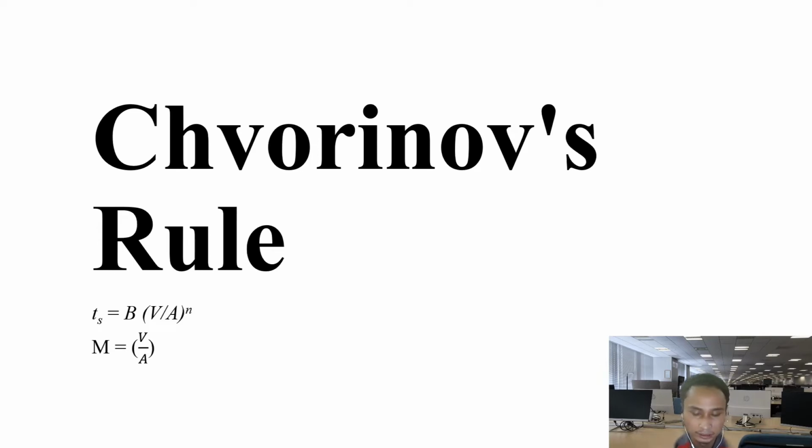The mold constant B depends on the initial temperature, density, thermal conductivity, heat capacity, and wall thickness of both the metal and mold. The unit of the mold constant B is seconds per meter squared. So that's all for me.